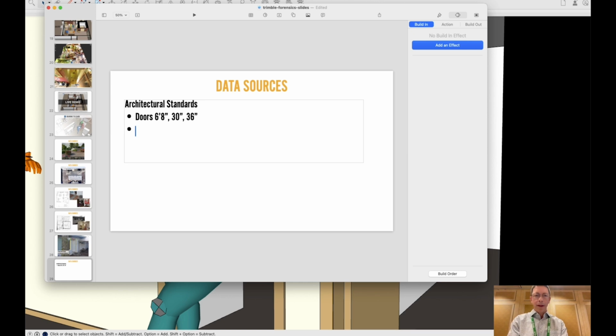Stairway. Okay. And what are some common things for stairways? 48 inches wide. And then there's a variety of rise and run that it could be. But if you're thinking about it, it's probably 6 or so, maybe 7, depending. So it could be 7-11 rise and run, or something similar. Could be 6'12". What else?